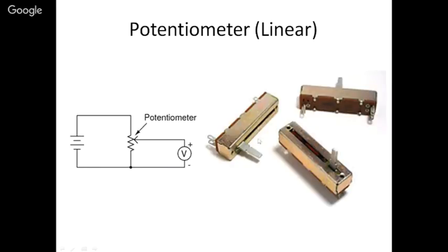Now what you see in this screenshot are linear potentiometers, or linear pots. All three are the same. What you see here is the wiper. This wiper can be moved from left to right, like the volume control of a radio. And this is the back side. Here we have different contacts, 1, 2, 3. Typically this is called 1, this is called 3, and this is called 2.